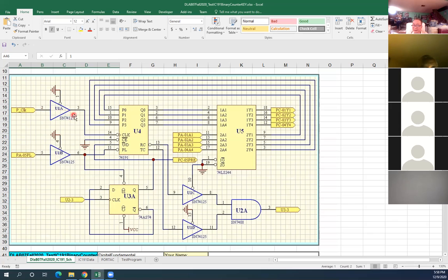U1 must be working. So that's why you can get a correct result for test number 1 and test number 2. And this U5 here, we already tested pin 2 for 1, then 0, pin 4, 1 or 0. That means nothing can be wrong in here.